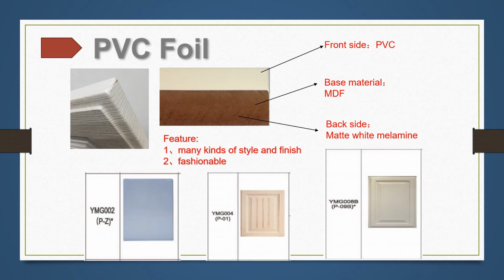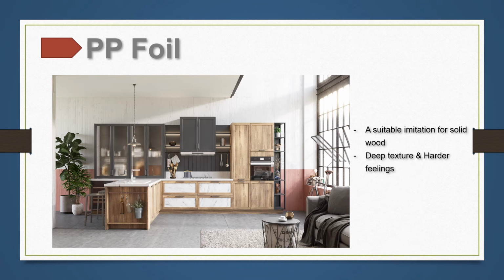Laminates can be understood as a melamine plus. Instead of using a piece of paper, now we have several pieces of paper, including a top one with ink, several layers of craft papers as the body parts, and titanium powder papers to make it stronger, and so on. Through a high pressure and high temperature process, a solid laminate is formed. The thickness of this layer is usually about 0.6 mm, depending on the layers of craft paper used. Together with the 18 mm thick particle board, the overall thickness of a laminate door is about 19 mm, so it's a little bit thicker than a standard melamine door.